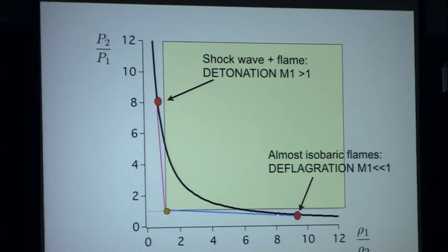There's also a big difference if you look at the solution of this thing, is that this thing is what we call a deflagration. It goes very slowly. Paul talked about it this morning. It's constant pressure, very low speed. So here you will have a flame front propagating at 50 centimeters per second, maybe 1 meter per second. And you need to keep that in mind, the order of magnitude, very small, very slow. And here you have something going at 1.5 kilometers per second. Okay, different world. Okay, so detonation again is not something you use in most civil applications. It's important for safety, and we try actually to build engines which use detonation today, but it's quite difficult.